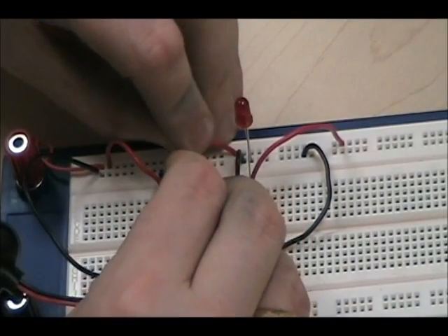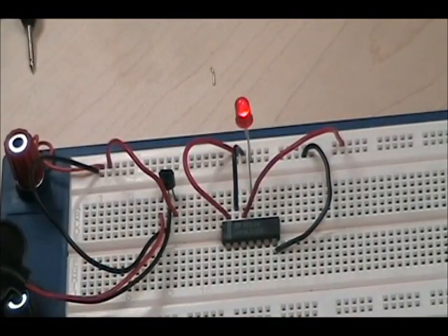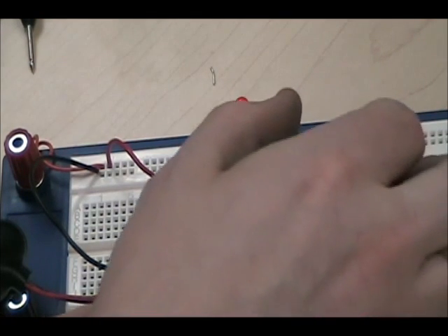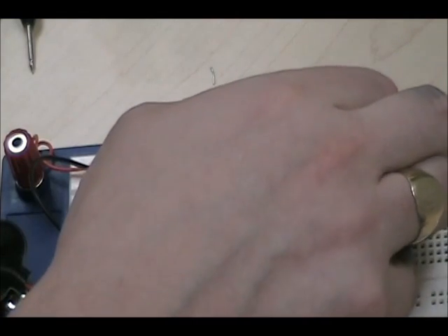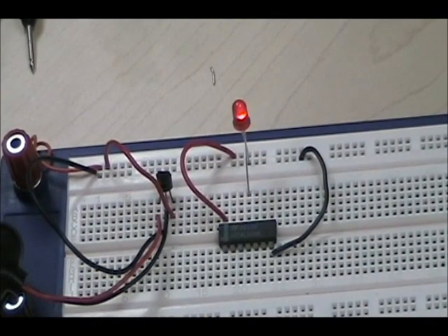As soon as we connect that other input to 5 volts, the output goes high. Now notice something. If I take both of the inputs and leave them alone, don't plug them into anything, the output stays high. I'll tell you why that is. With TTL, with digital circuits, normally, not in all cases, but most of the time, if an input is not connected to either 5 volts or 0 volts, by 0 volts I mean a very low signal or the ground line, then it will automatically assume a logic of 1.